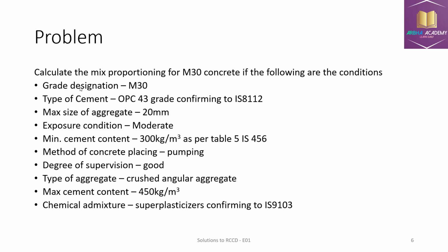There are no restrictions that you can adopt any mix design in the world, and you can arrive at one particular value which can be used for the project. So there is no restriction that you need to only use IS code or IS mix design guidelines in India. No, it is not. So if the mix design value is approved by the client, then there is no restriction at all.